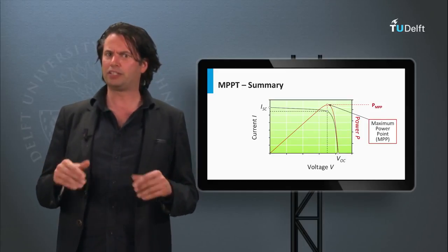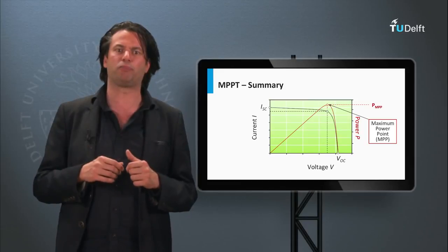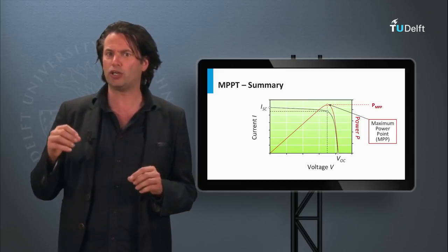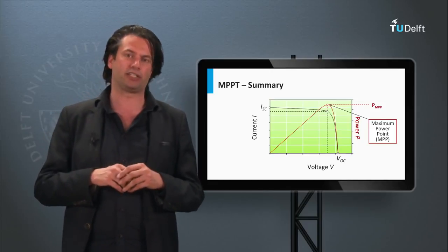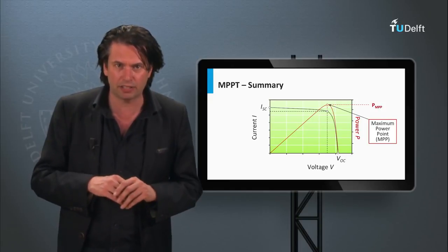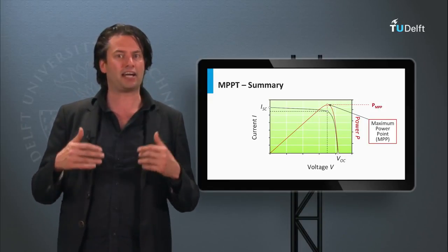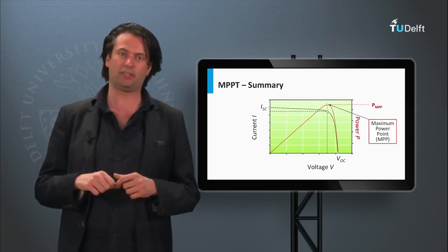In doing so, the device is expected to use as low an amount of energy as possible so as to not undo the additional energy gains the maximum power point process provides. The device is also expected to respond swiftly and accurately to the changes in the ambient conditions that impact the PV output.